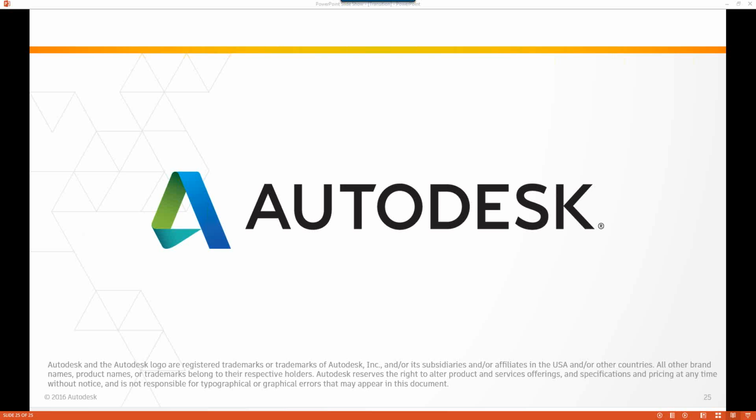Yeah, that's one I was actually in the middle of replying to, so thank you for bringing that one up. Actually, the answer for that one is no. Simulation Mechanical has the ability to scale results after the analysis is completed. Now, in In-CAD, we do this a little bit differently. You have the ability to set up all your subcases beforehand, and because it's the same model and all you're adjusting is the loads, Nastran actually cranks through all of those subcases very quickly, and you'll have all the output for those subcases at the end. That's currently what it's doing. I know we are looking at expanding our post-processing capabilities a little bit, especially when comparing what we have in SimMech, but that's the way we do it today.